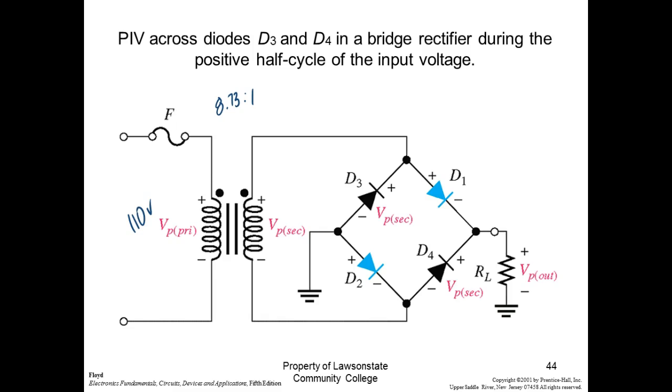Now you have to understand the math. They say, well, how do you have 0.73 turns of a wire? You don't. It's just that if the secondary had 1,000 turns, then the primary would have 8,730, right? You understand? Which would be a whole number of turns. So we're not doing half turns or quarter turns. We're just doing a ratio and it's always to 1. We wouldn't state a ratio of 8,730 to 1,000; we would divide those out. So this one has a ratio of 8.73 to 1. So it's a step-down transformer.